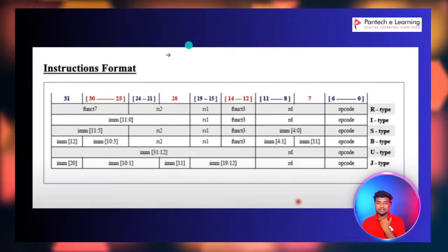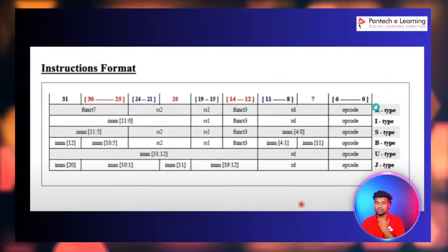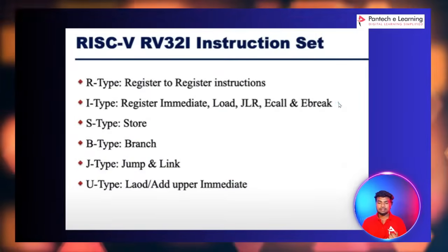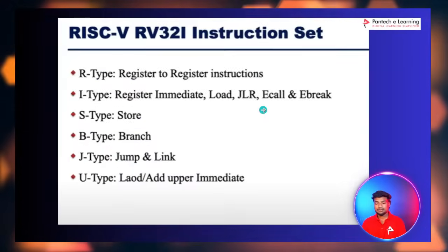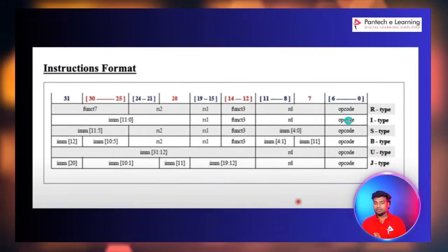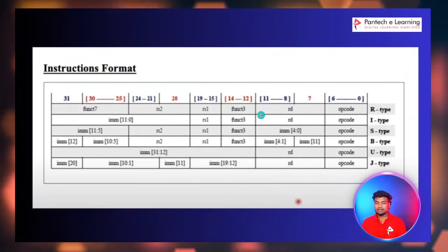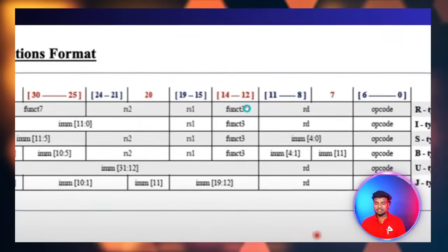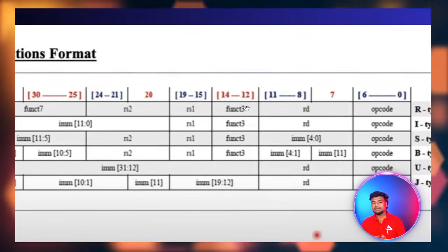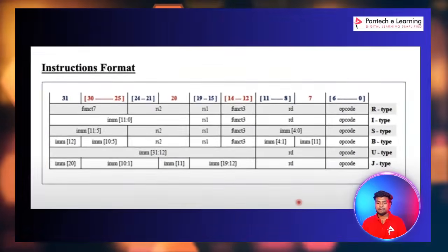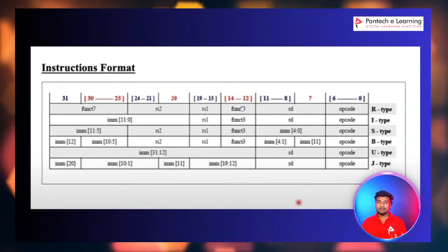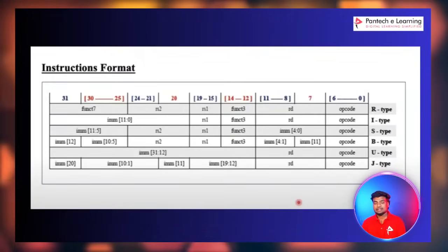And then this is the instruction format. I already said this instruction has a 32-bit width. Bits 0 to 6 are the opcode, and then read or write, and then the functions. Each of funct3 and funct7 has some separate operations. If you read the ISA instruction list, you can easily understand.